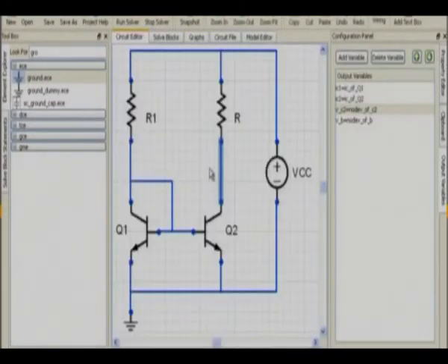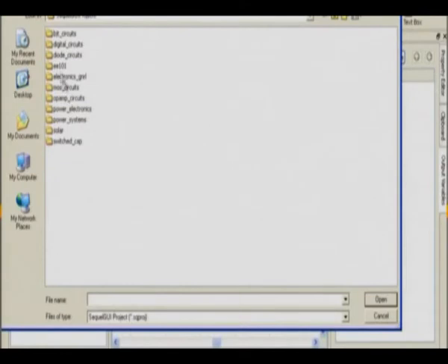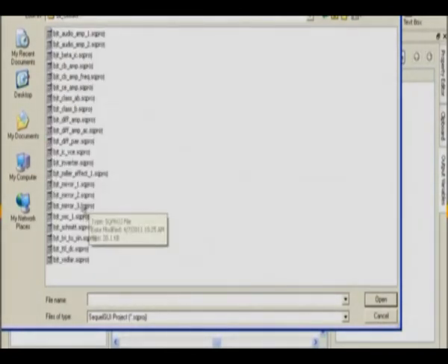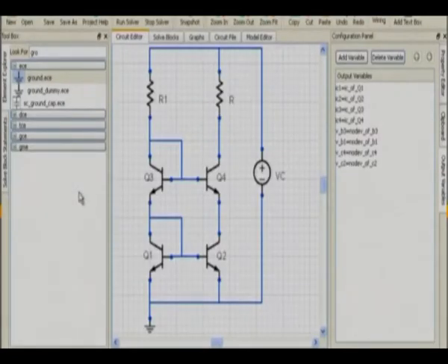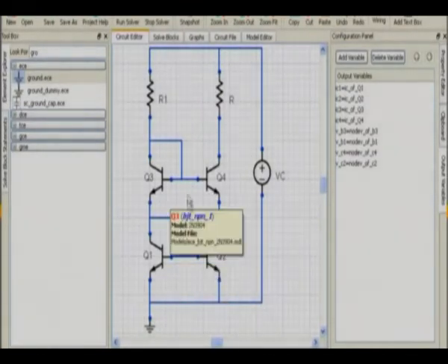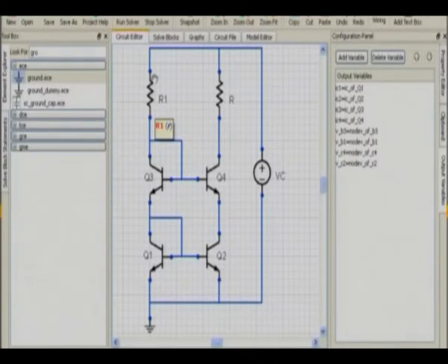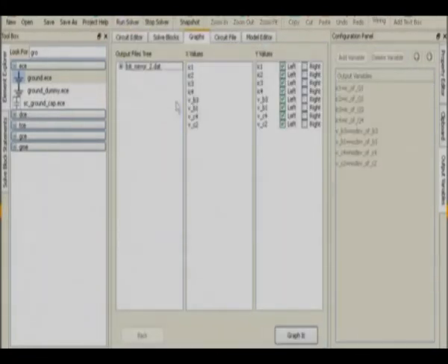So that is not very desirable. Although the variation is small, it is not very desirable, and that's why there is an improved BJT mirror which is used, and that circuit is BJT mirror 2 in this particular set. So look for BJT mirror 2, and that's a cascode mirror. Here once again the objective is to design a certain output current, and we want it to be independent of this voltage here. Okay, so let's run this solver and see how this performs.